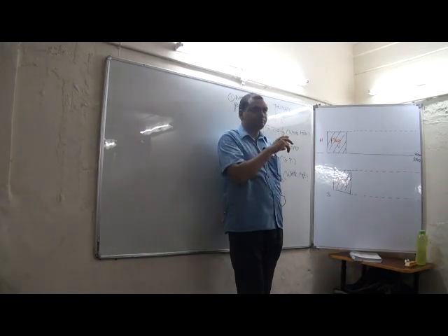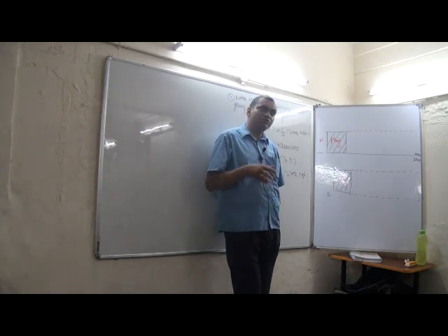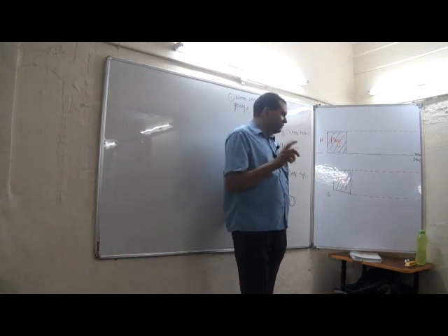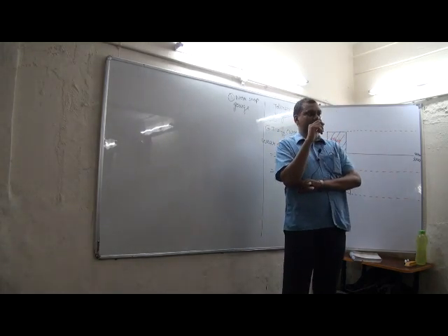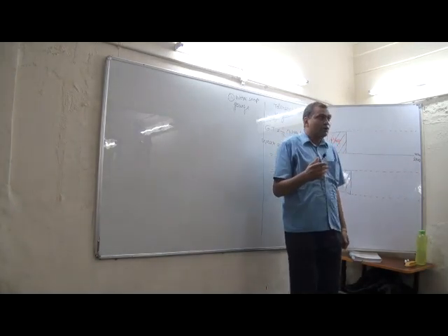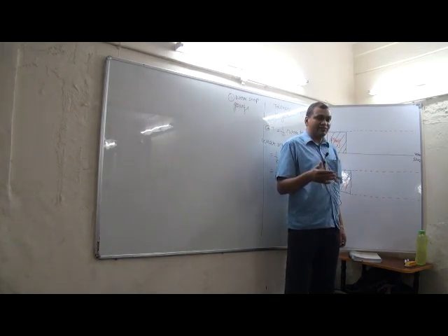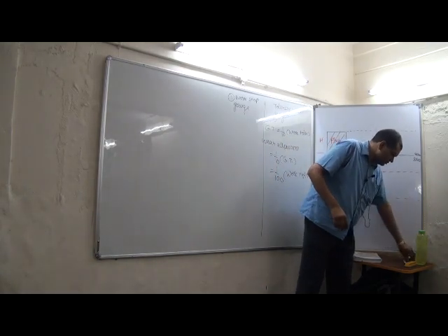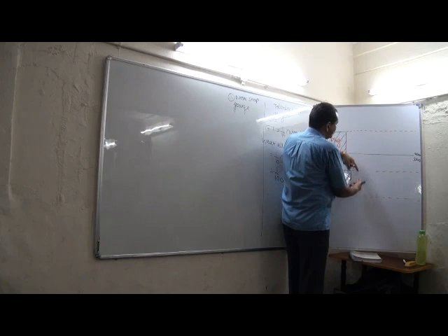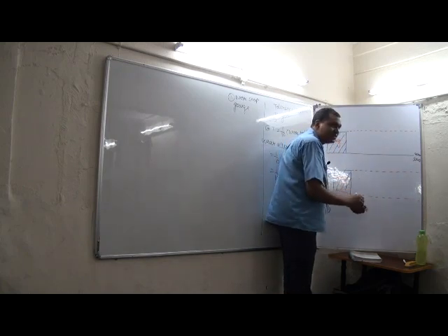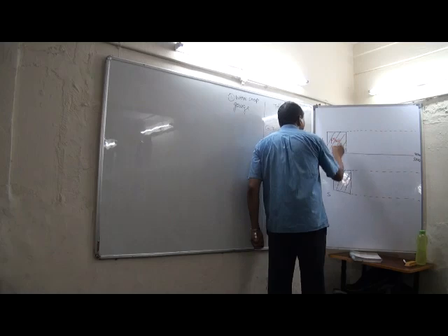The first type of gauge is the workshop gauge, or the gauge for the workshop department. The philosophy of the workshop department is that we will not produce anything defective. So due to that philosophy, the tolerance on gauges will be towards the work tolerance. As we discussed yesterday, the go gauge will be designed here and the no go gauge will be designed here.